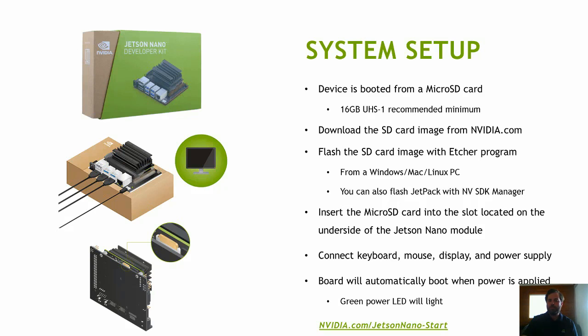The first time you boot up with a new SD card image, you'll need to go through some basic setup steps with Ubuntu, like entering your desired username and password and setting the time zone, similar to what you would see setting up Ubuntu on a PC system actually. For this initial configuration, you'll need to have a monitor, keyboard, and mouse connected, but after that you can operate it headless if you want. And in the next version of Jetpack, we're adding support for headless setup, so you won't need a keyboard, mouse, or monitor at all if you don't want.